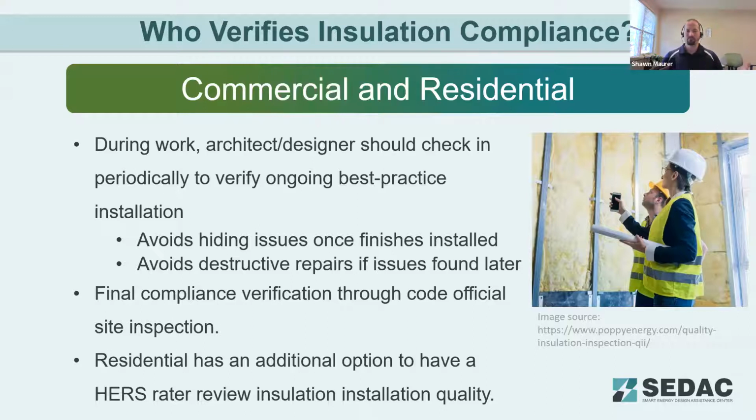A big thing that we commonly find is if we wait until all the insulation is installed, sometimes issues get covered up, especially issues with air leakage through the envelope into the insulation. And so if you're spot checking this work throughout the process, sometimes you can catch those issues ahead of time, before they get covered up, and avoid destructive repairs later if testing finds a problem.